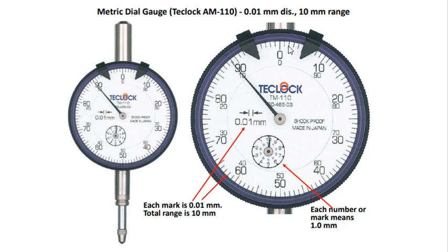Each revolution of your larger dial indicator is going to give you 1 marking in your small dial here. So each marking in this little dial is going to give you 1 millimeter, and we have 10 of them. Therefore, it's going to measure up to 10 millimeters. That's the capability of this dial indicator. Of course, you can call this a dial gauge. It's the same thing. And this is a full instrument that you can see from top all the way to the contact.